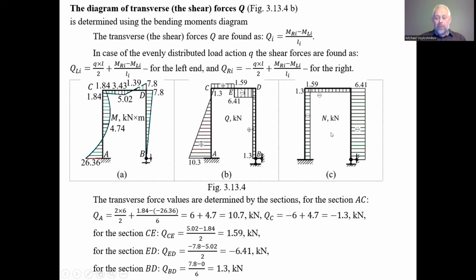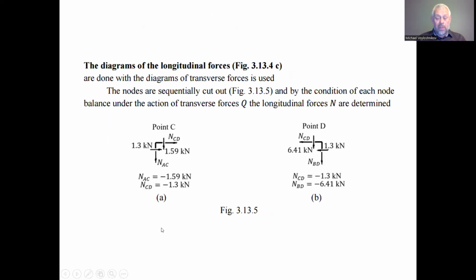Yes, and the diagram of the longitudinal forces. To find the longitudinal forces, usually we have to cut off the nodes. So we consider the nodes and the balance equations for the nodes. For one node, point C, we consider the transverse forces. We know from the diagram of the transverse forces, and we have to find the diagrams of the longitudinal forces. They have to be in the balance in the nodes. This is for the rigid connection, but it is not so important here, so we do not consider the bending moments, only forces. We indicated the longitudinal forces here for the case of the rods stretching, not compression.